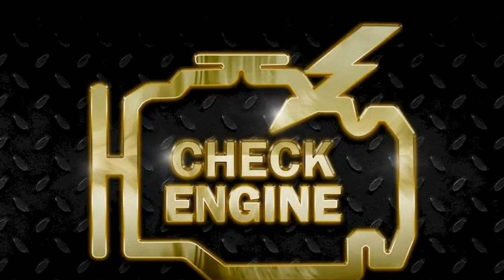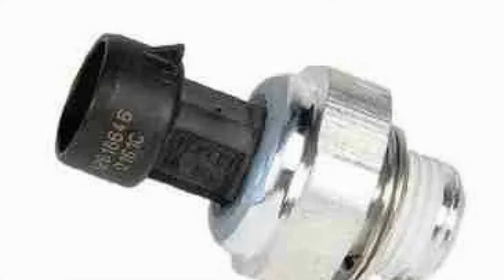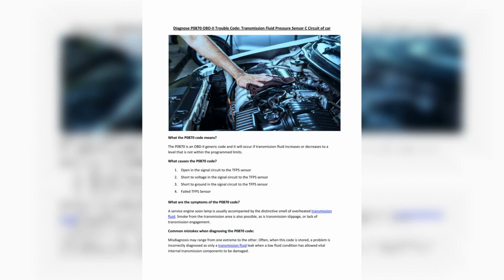Common errors when diagnosing code P0870. Code P0870 can cause many errors, as it can give a technician the impression that the only problem is a transmission leak. That's why the first step is always to carry out a thorough diagnosis on the transmission to make sure that the high temperatures haven't damaged it internally. Only when the transmission has been fully assessed and repaired should sensor diagnostics be carried out.